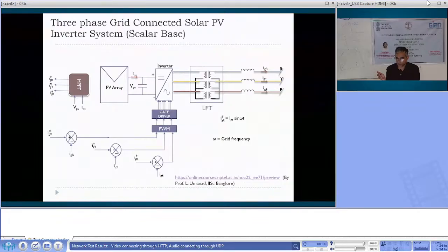So now we move to the control of the inverter, in which you have to generate the reference to compare with the actual values. Generation of the reference is through MPPT, so this decides what exactly it should work at now. It needs input, which is the output of your panels.